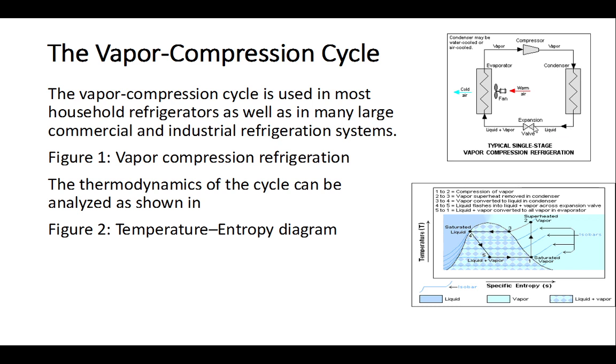So we've got the valve here, and again, pressure builds up behind the valve, and on the other side there's a low pressure. So with this low pressure, the liquid can vaporize, and in order to vaporize with this lower pressure, it needs to absorb energy. So we've got warm air. This is the calories, the energy which we need to turn this from liquid to vapor. So this goes past the evaporator, and we get cold air coming out of the evaporator,